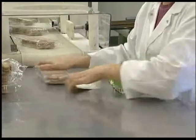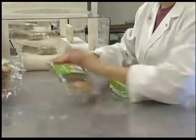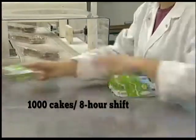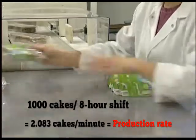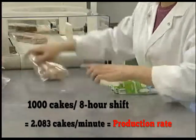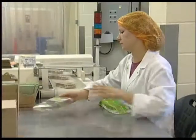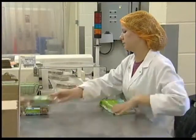Step 2. Determine the production rate. That means how many units per unit of time. For example, you want your factory to produce 1000 cakes per 8-hour shift, or 2.083 cakes per minute. This is called production rate. You need to be careful because a higher production rate can lead to a decrease in quality.